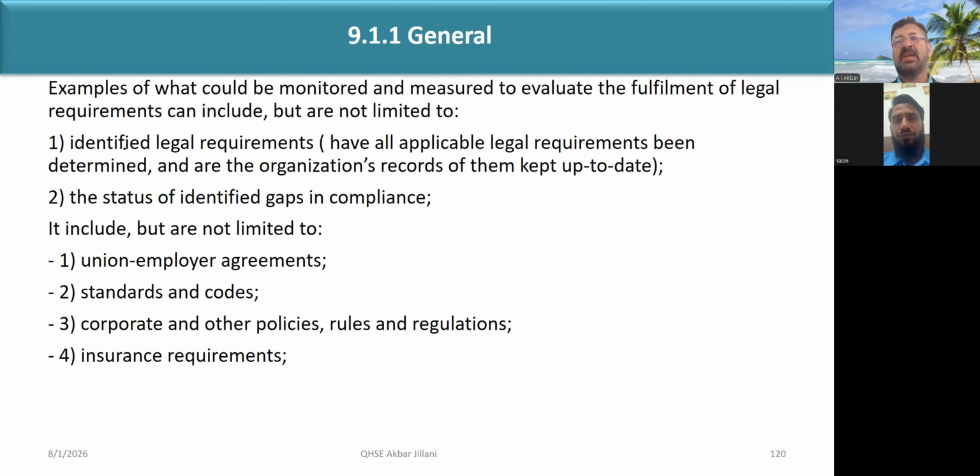Article 20 is telling us that all the lifting equipment will be inspected by a third party, like the crane, the forklift, and the elevator, after 1 year. But the elevator after 6 months. Clear? And the crane and the forklift will be after 1 year. Clear? Now the third party inspection certificate of this.